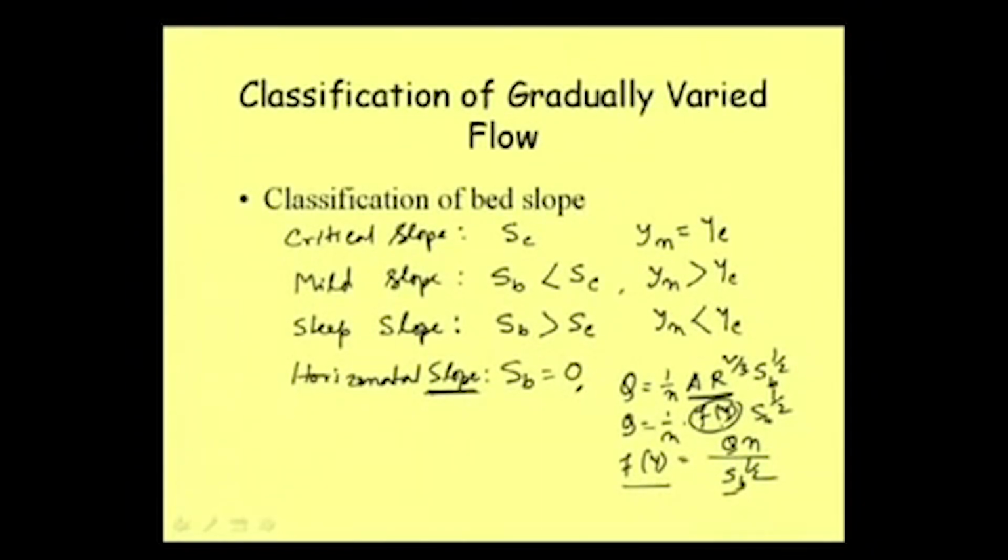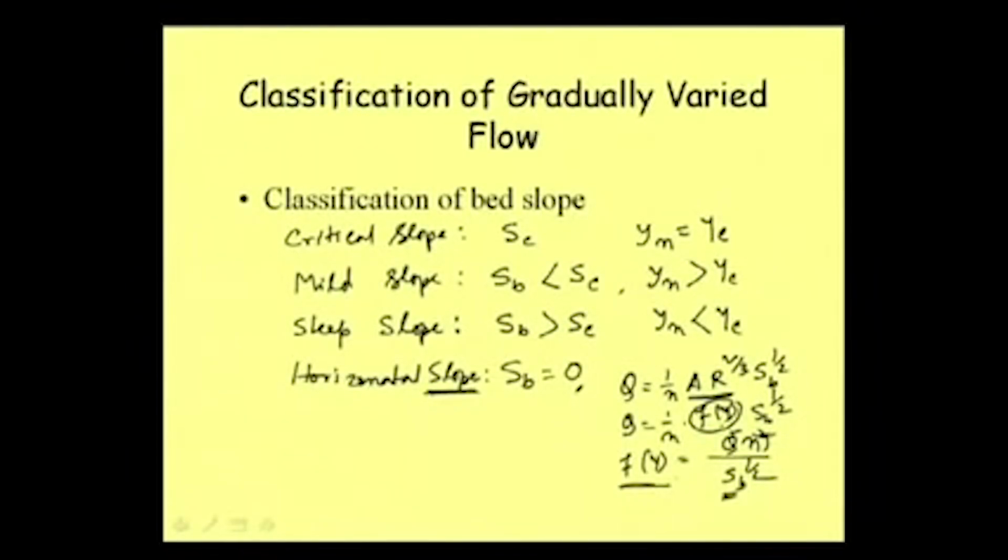But this being a function of y, we can see that if we put S_b equal to 0, then Q, the discharge, is having some positive value, so this part is divided by 0. So, that term is becoming infinity. On the left hand side, other than this, we have the sectional dimensions like b, and side slope z if it is a trapezoidal one, then we have n and other things remaining fixed. Suppose y_n will remain on the left hand side.